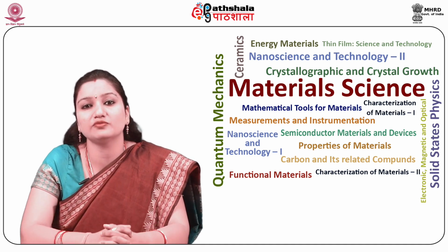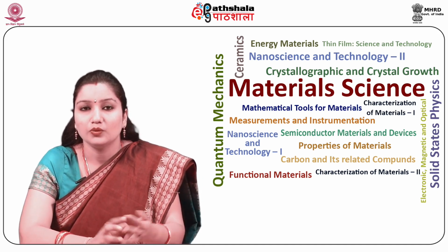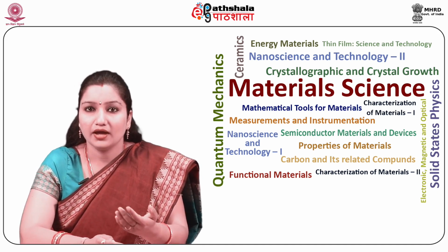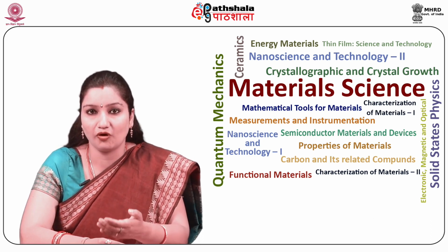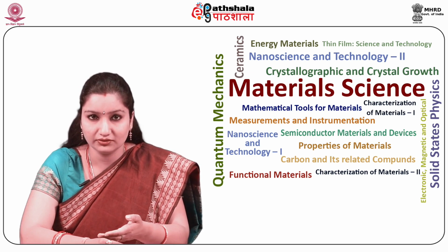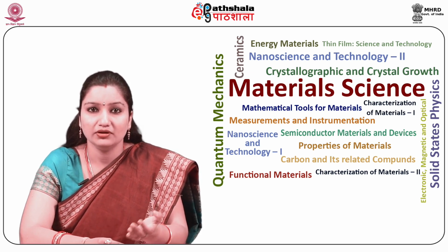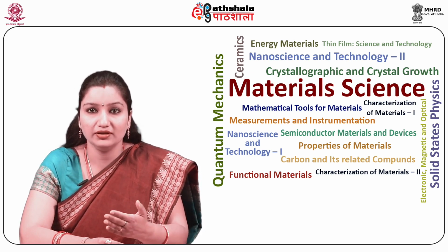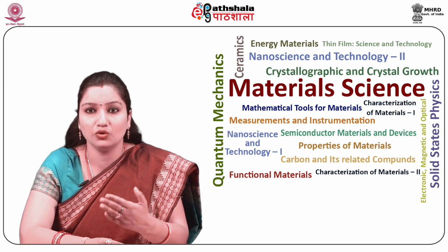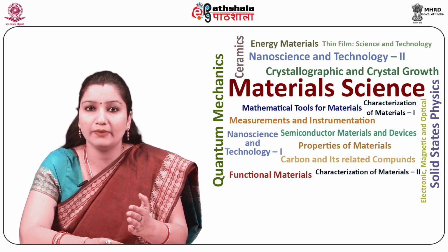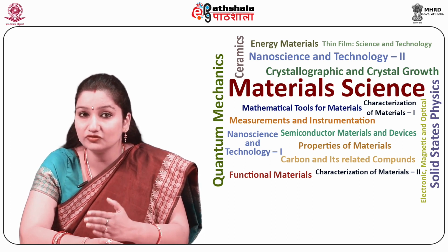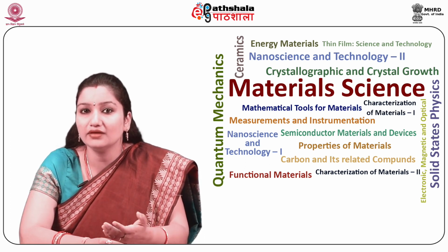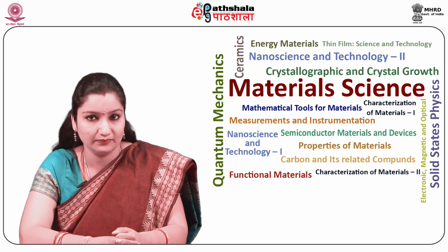for the hardest materials. With this system, a hardness number is determined by the difference in depth of penetration resulting from the application of an initial minor load followed by a larger major load. Utilization of a minor load enhances test accuracy.